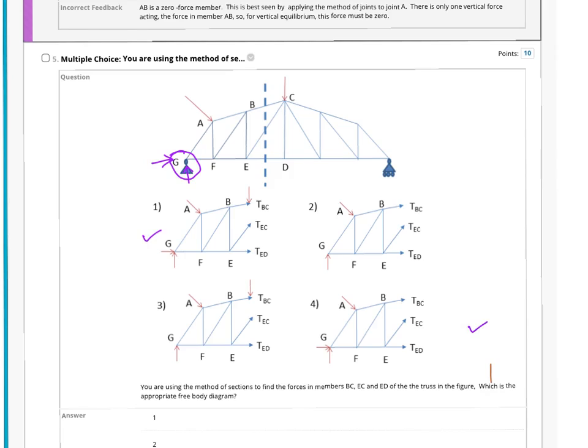Okay. Now if you look closely at all the other forces that have been applied, between these two forces that I rightly applied, all the forces are shown tensile, so that's okay, but the force at C is wrongly put in this case. So this is not the right diagram, this is indeed the correct free body diagram.